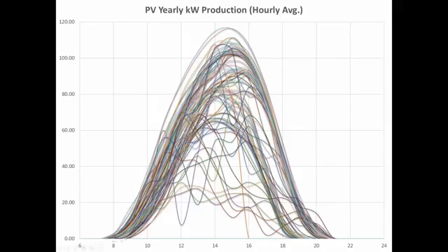And as you can see, most of the production starts around 9 a.m. and it essentially ends anywhere between 6 to 8:30 p.m. And this large shift is also because of daylight savings and the fact that we are in a northern latitude, so we do have later sun in summer. We do see a shift. Plus, we have an hour time change that causes the production time to shift around. So that has to be factored in when we are doing the yearly analysis.